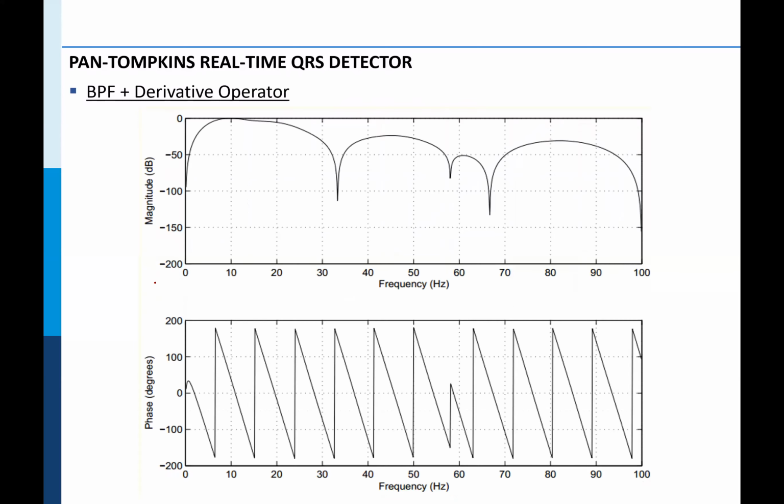Okay. Now, the combination of the bandpass filter and the derivative filter, which is stage 1 and stage 2, the response is shown there, and it's all easily derivable. Okay? Because when the filters are put in cascade, the impulse response also gets added. So it goes back into the basic concepts you would have seen in signals and systems. By adding filters in series or in parallel, what happens to the impulse response and transfer function? That's exactly what we are noticing.